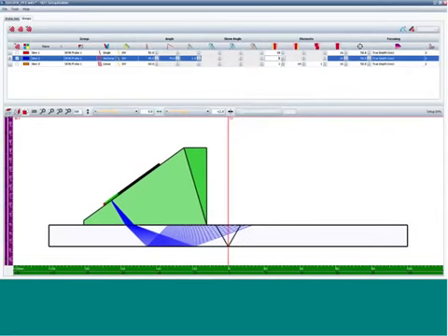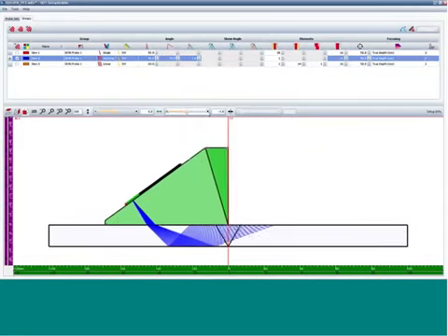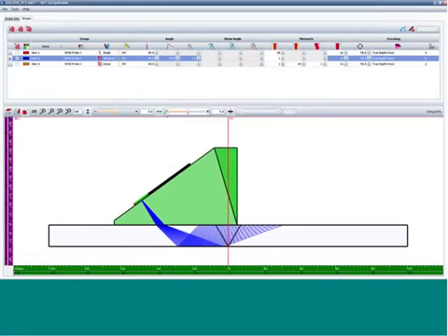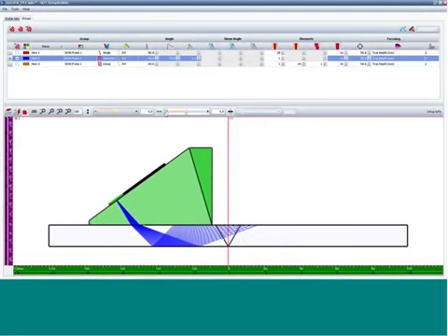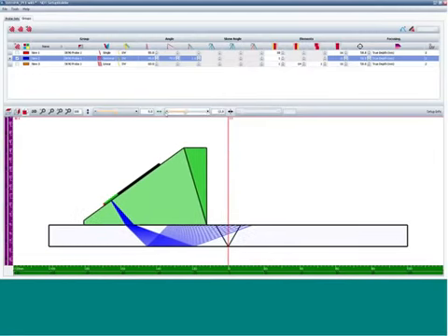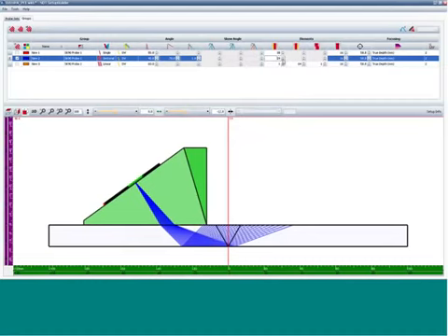I'm further away from the weld. So I can either move the probe closer to the weld, or from my normal inspection position, I can move the aperture inside to an appropriate position.